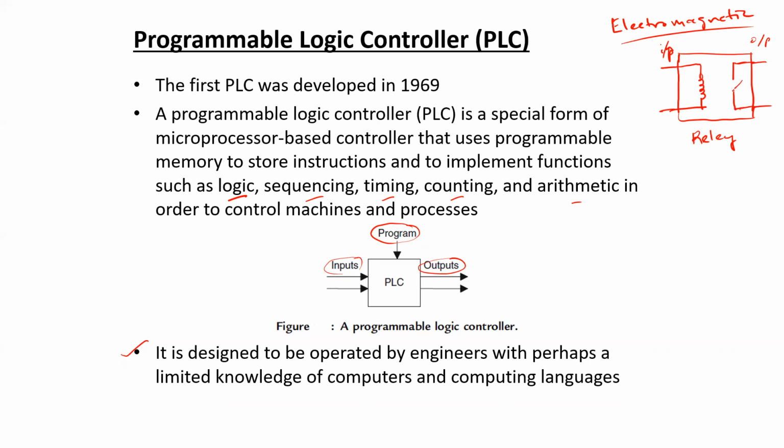So I have here designated a normally open contact in terms of a switch. This contact at the output side will close when this particular coil is getting energized, when there is some current flowing through the coil.